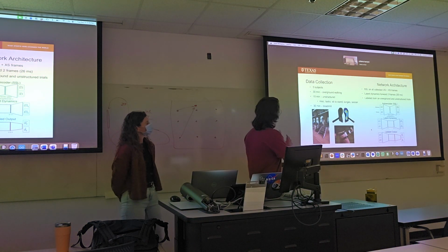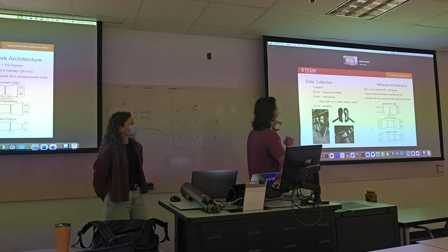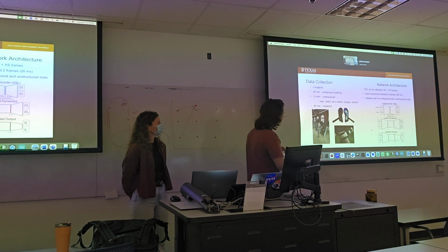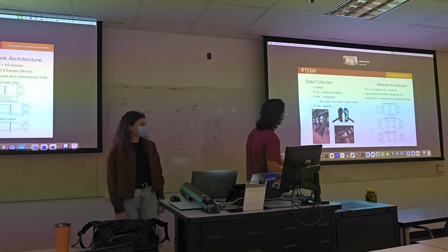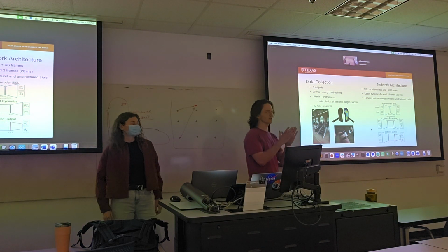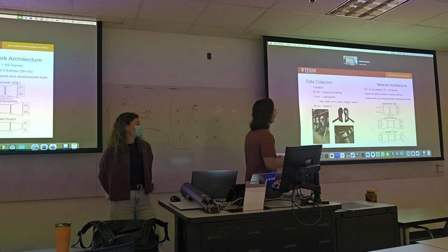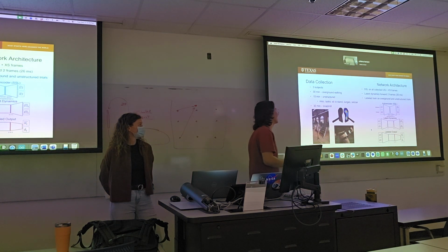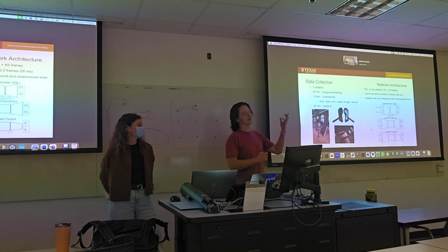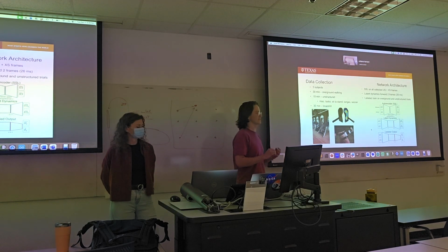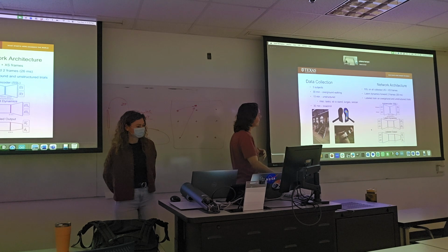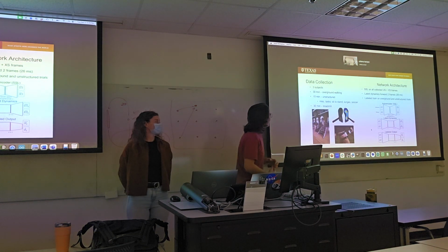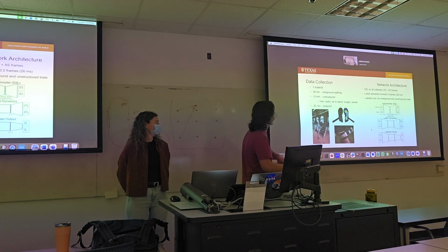So using that treadmill data set as well as the other ones, we do self-supervised learning over all of it. Then we take those model weights and pass them over to a very slightly different model where we shift the labels forward 2 frames, which converts to about 26 milliseconds. The purpose is that if we're looking towards prosthesis control, there are a lot of delays involved, and you want that to be as snappy as possible, so if we can get toward future prediction, it's very valuable for us.